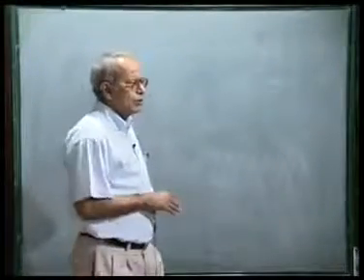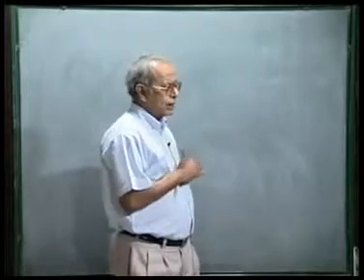Let me now summarize what we have learned today. We started our discussion with higher pair mechanism, namely cam follower mechanism. We will be discussing only 2D or planar cam follower mechanism. We defined the cam and the follower, and we have also classified cam follower systems based on three things, namely the type of cam movement, type of follower movement, and the type of follower surface.